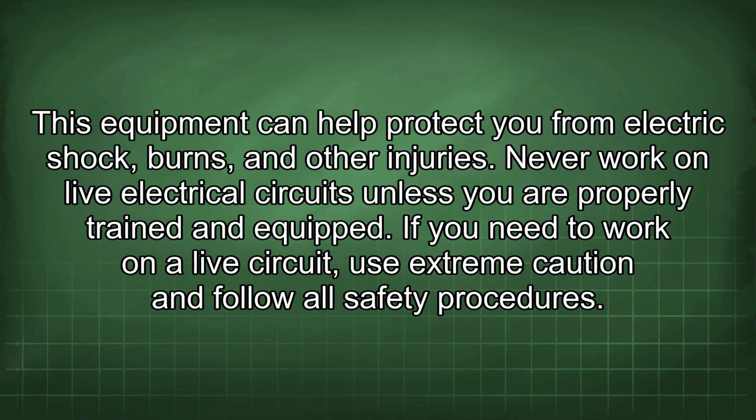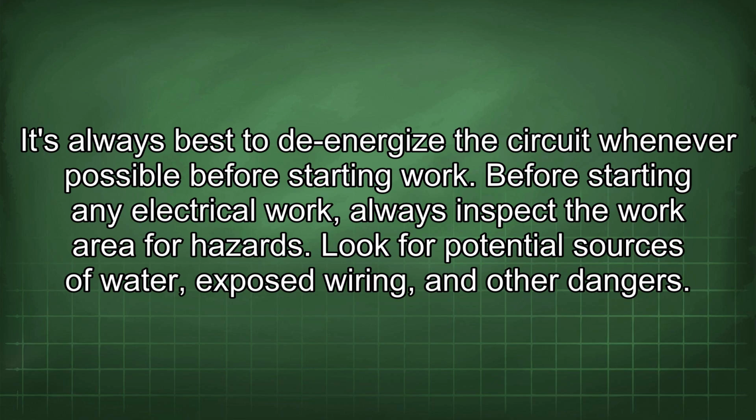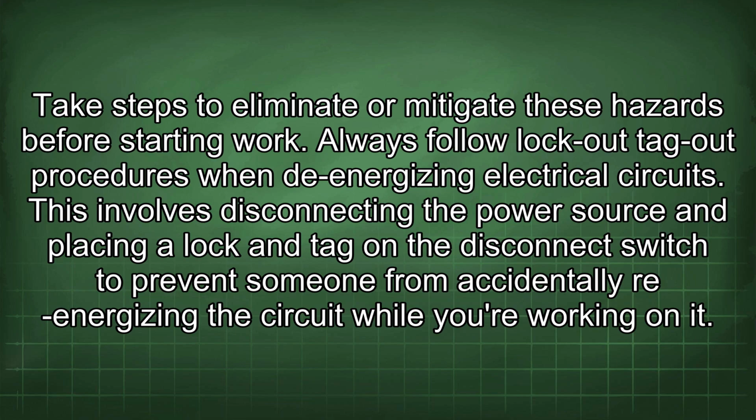If you need to work on a live circuit, use extreme caution and follow all safety procedures. It's always best to de-energize a circuit whenever possible before starting work. Before starting any electrical work, always inspect the work area for hazards. Look for potential sources of water, exposed wiring, and other dangers. Take steps to eliminate or mitigate these hazards before starting work.